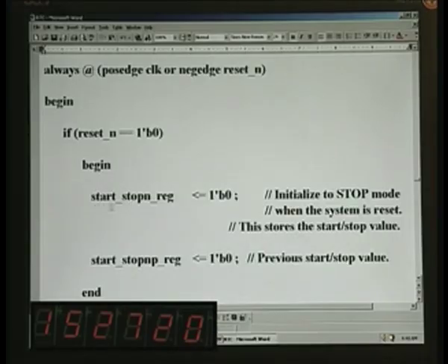So, you can use it for a dark room, you can develop your films, etc., using this precisely same real time clock in the down count mode. Even the up counter you can use, and there is going to be a buzzer after the set time has lapsed, and it will freeze at the last value. If it is down count, it will be all zeros and stay there, and the buzzer will sound for 30 seconds and be silent thereafter, but the output itself will remain high. And